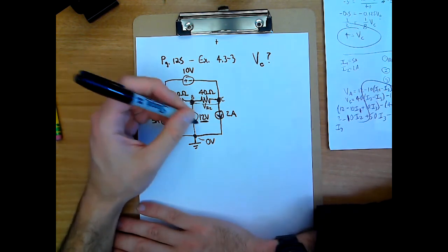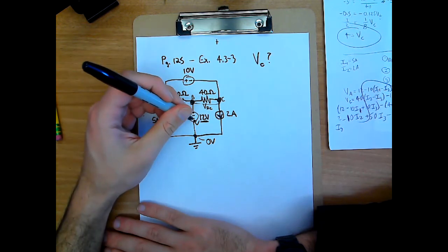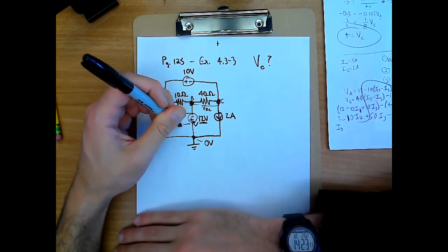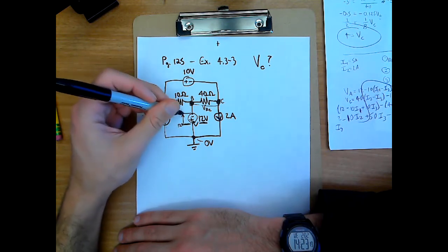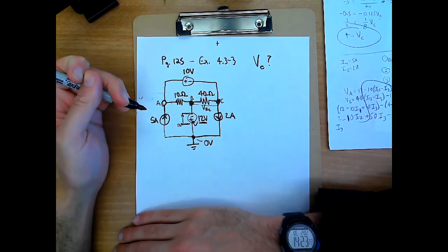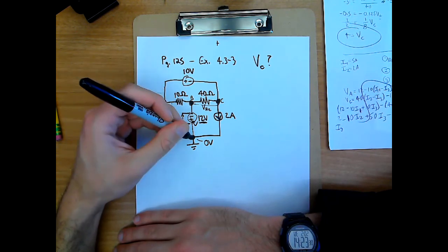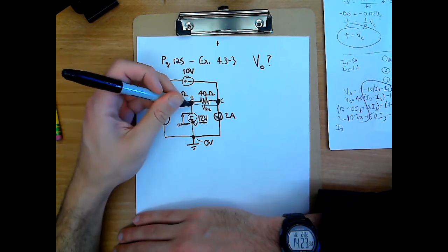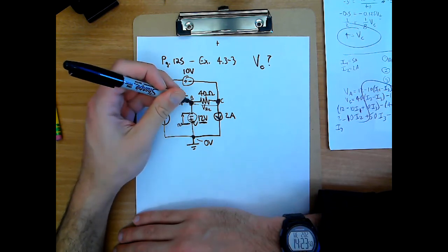That specification always applies to the voltage that's applied by the positive end, the plus end of the source, relative to the negative end. So if I measured across this source, it'd be 12 volts from this end to that end. If this was a negative 12, it'd be negative 12 volts from this end to this end. The specification's always for the positive end relative to the negative end of the source. So VB is then, if I go from 0 to B, I'm starting at 0, going down 12 volts. Or if I ask what's the voltage at B relative to 0, it's 12 volts below 0. So you dropped 12 volts going from 0 to B. Okay?